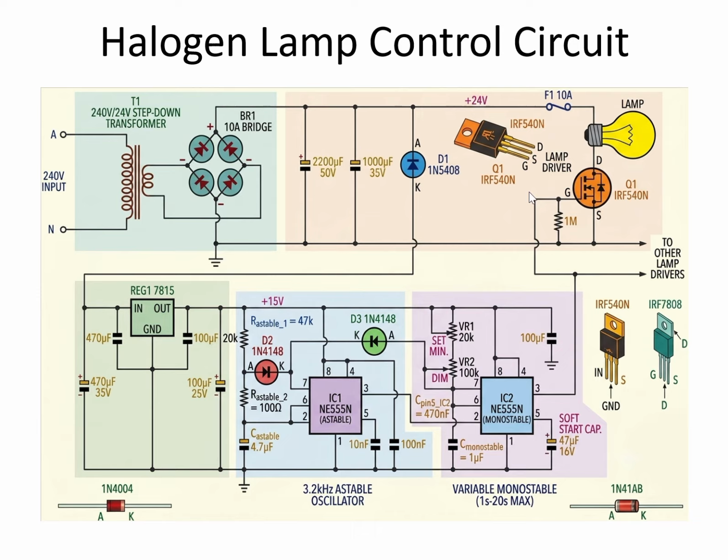The next one is the oscillatory circuit. It consists of a 555 IC timer and diodes. This is D2 and this one is D3, two diodes here, and other resistances. This 555 IC continuously generates square wave pulses at approximately 22 kilohertz.